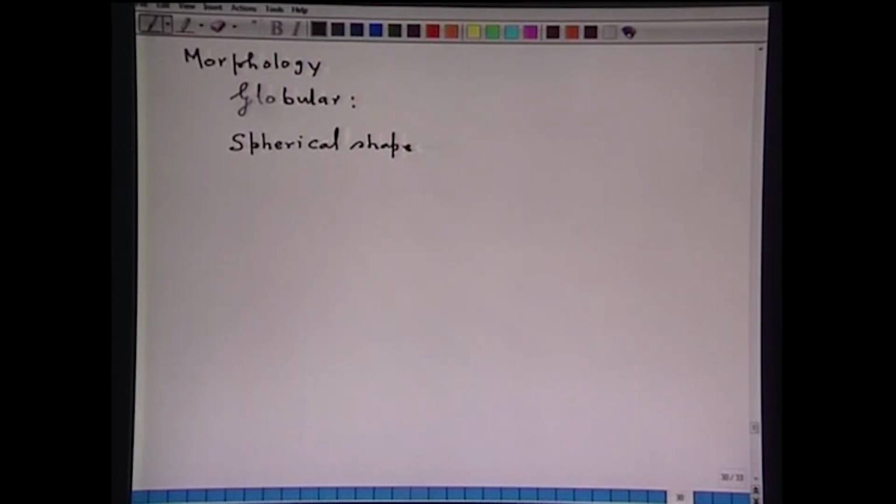Manganese sulfides and oxysulfide inclusions, they formed during solidification in the interdendritic region are also globular in nature. So that means the globular inclusions are a little less harmful. That depends upon where they form, because inclusion can form either during solidification or during tapping or teeming of steel.